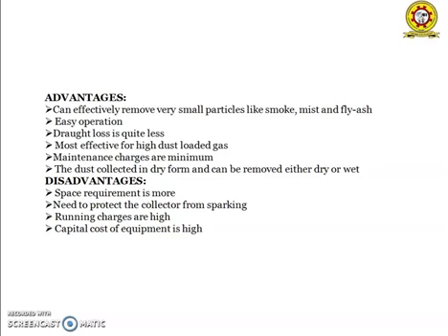Coming to the disadvantages, the space requirement of the electrostatic precipitator is very large. We need to protect the collector from sparking. Running charges are very high and the capital cost of the equipment is very high. And if you want to replace one part of the electrostatic precipitator, it requires more cost.